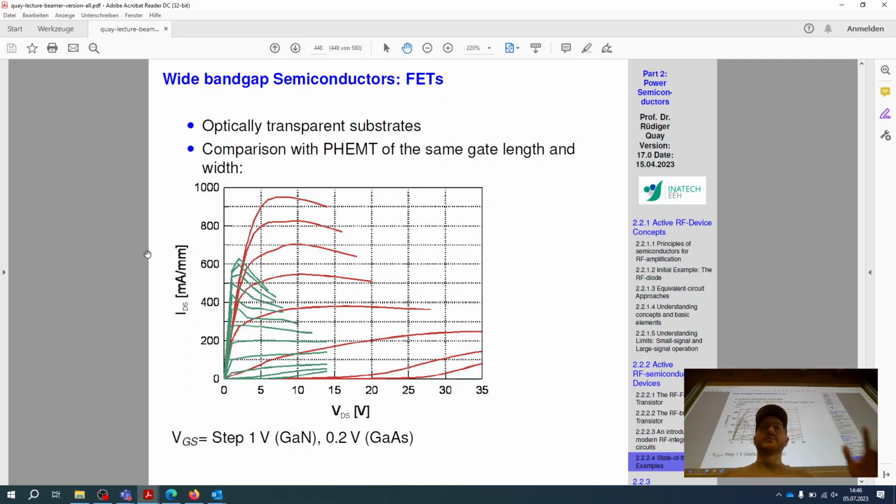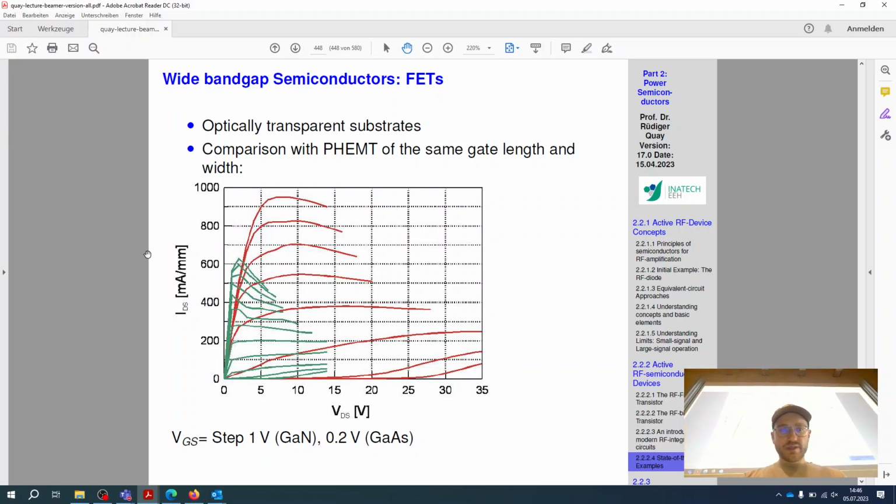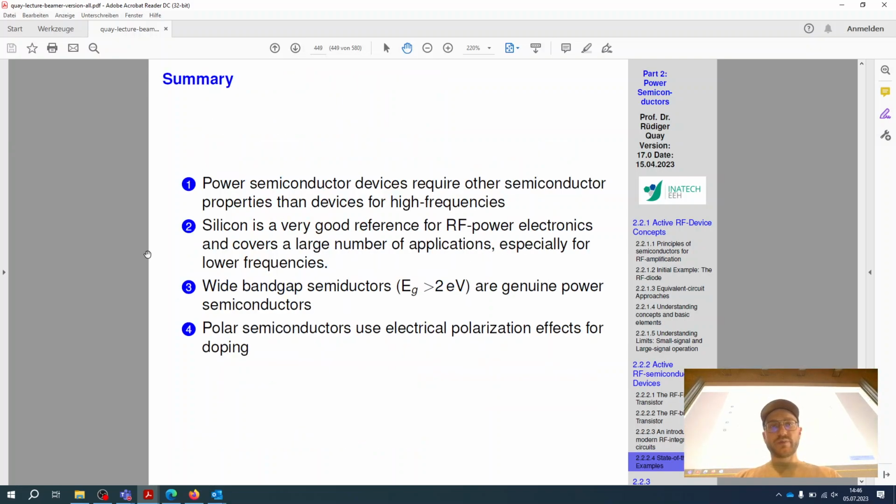I think the plot here is a bit not always the case like that. If moving to the higher frequencies, you can see that there's an opposite, once GaN reaches its fT. But still, what this plot tries to make apparent is that the higher band gap, higher voltage, thus higher output power for a specific frequency. If we move from 100 gigahertz to 1 terahertz, this will be the opposite because GaN cannot reach 1 terahertz due to the reduced mobility of the carriers.